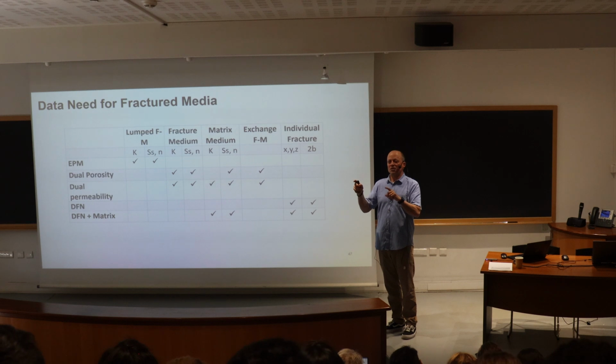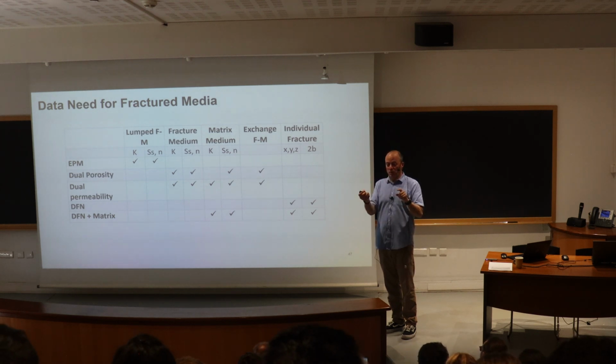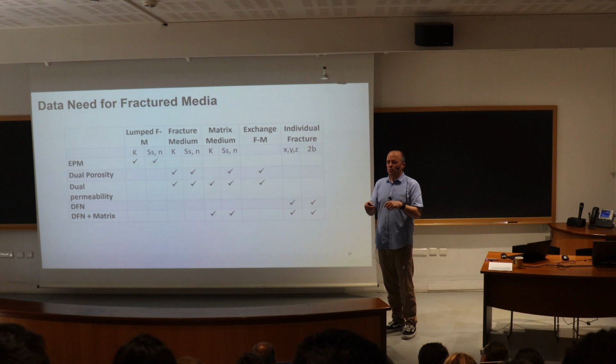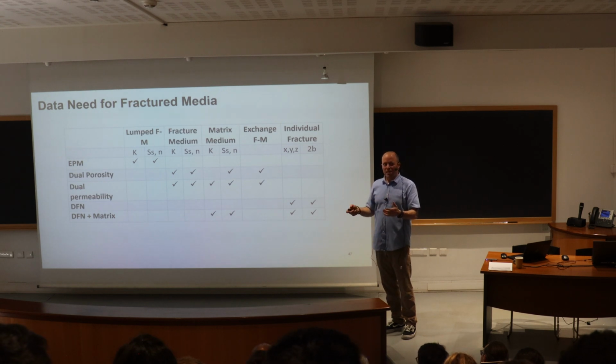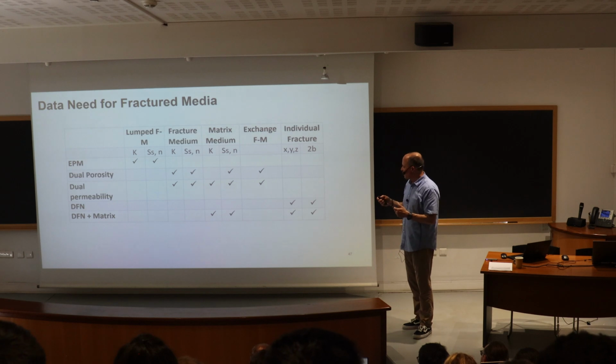Very similar to Darcy's law, because you will assume that there's a hydraulic conductivity in the fracture and a different hydraulic conductivity in the matrix. So there's a difference, and depending on the difference, flow will be from matrix to fracture or fracture to matrix. So you start to get more and more parameters that are required to be defined when you go to the more complex approach.